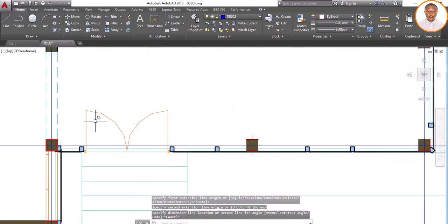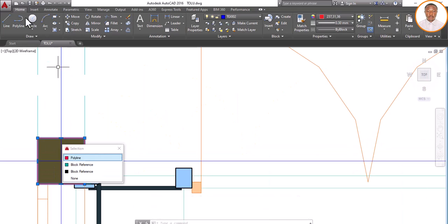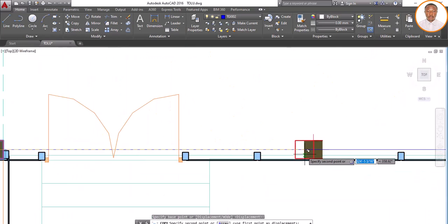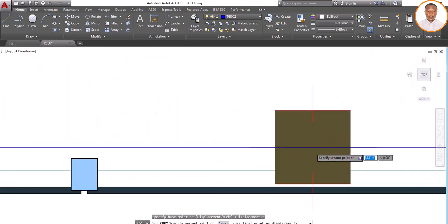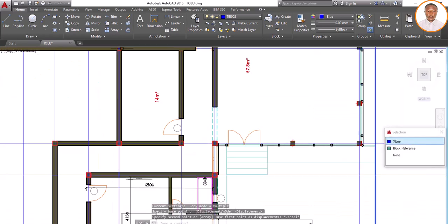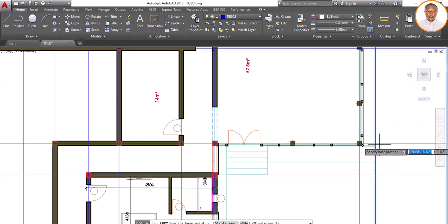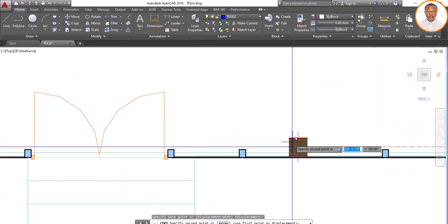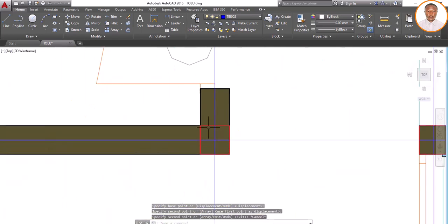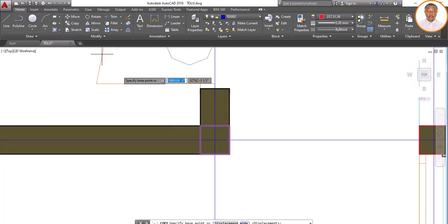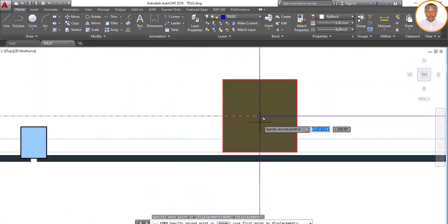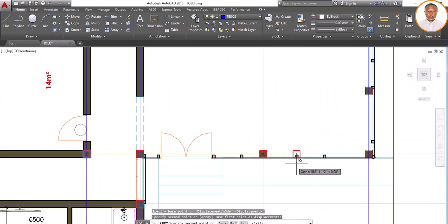So automatically at this point, I can put my column. Let me select this column, copy it from this center, and come and position my own column at this point. Then before then, I need my grid lines, my construction lines. So I copy it from the center of this place, this point of intersection, and bring it to this place of intersection. So that is that. So I now also copy my column, and from the center here, I position it here. So do you see it? So that's my column there.